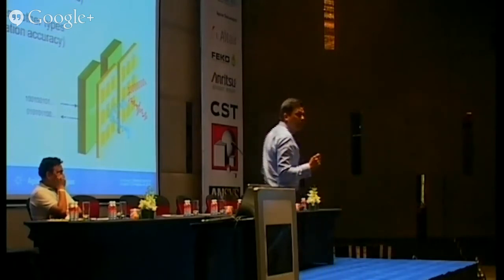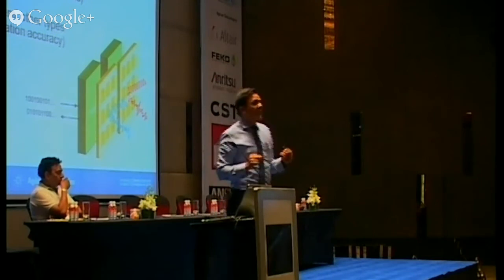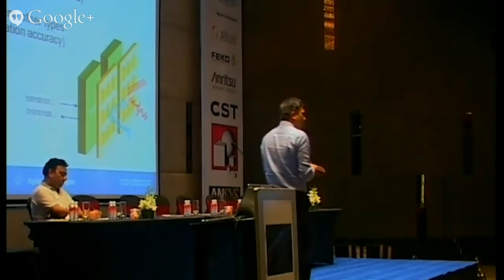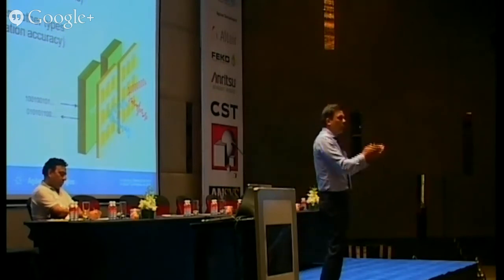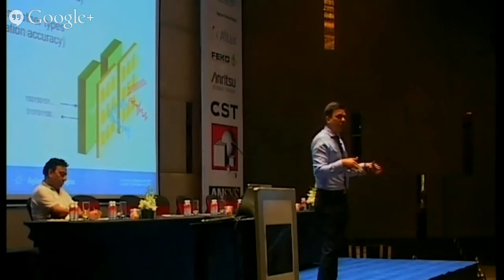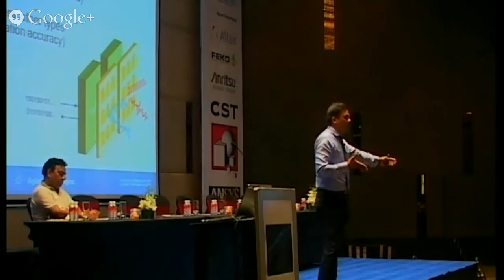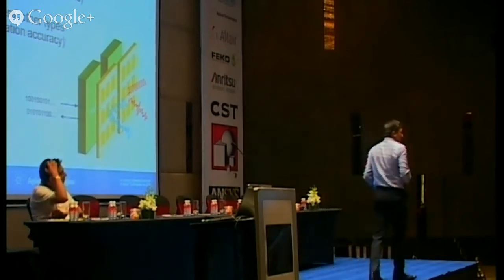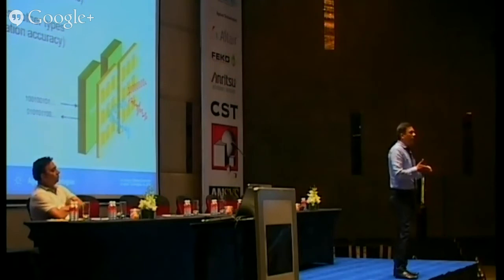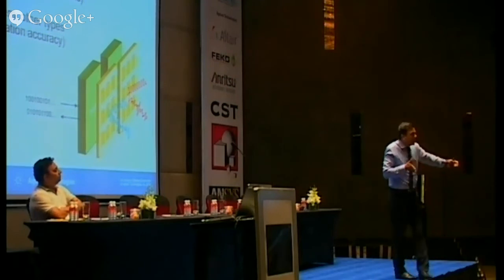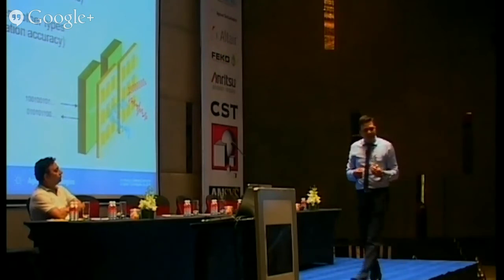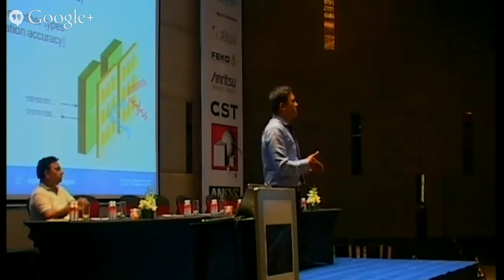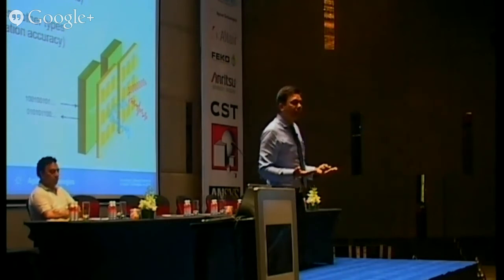And then the radars or these satellite applications are getting more and more complex. More and more complex in the sense, now we are not talking about narrow band signals. We are talking about wide band signals, because radar applications are using IQ modulated signals with very wide band, maybe LFM chirp, maybe IQ modulated, maybe Barker coded pulses, etc. And in satellites, people are going towards more and more wider bandwidths, maybe hundreds of megahertz of bandwidth. And in case you have to test these antennas for such applications, it requires a lot of deliberation.